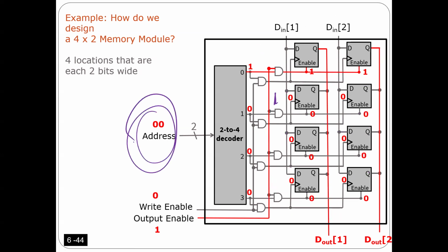That's why I have a decoder here. With the address you have here, I'm going to select either this one or this one or this one or this one. In this specific example, I put 0, 0. That's why I have 1 here, and that's why I'm going to work on this one. But let's continue. Here, I want to read. That's why I put out enable here. If we do that, the link is made, as you see here. Here we're assuming this unit has an enable input. Once you enable it, the stored value will be connected here. That's why you are going to read.